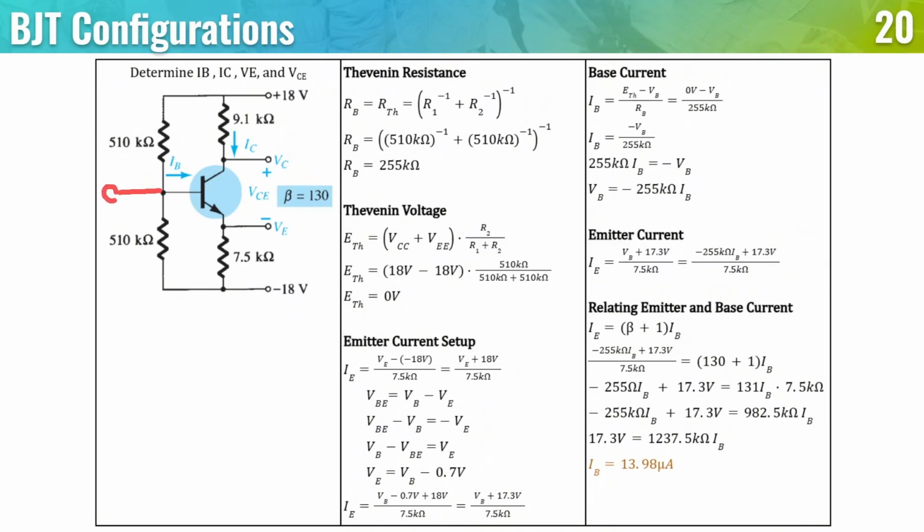Normally, if we have a V in here and there's no specified input voltage, we usually treat it as a ground. But since there is no ground this time, we have to take a different approach in computing for the Thevenin voltage and the resistance.